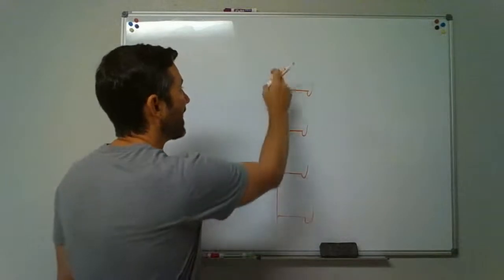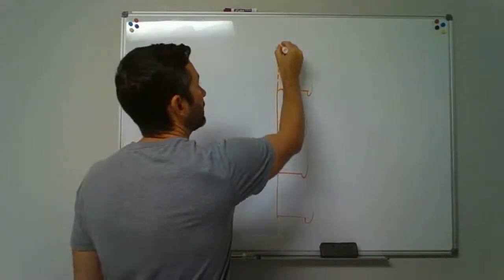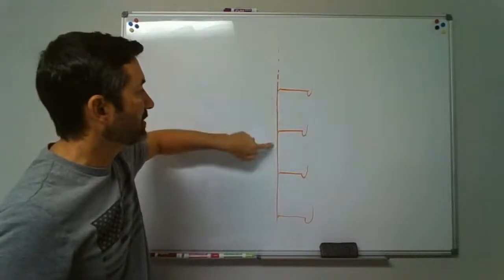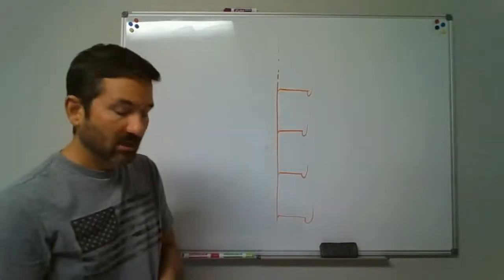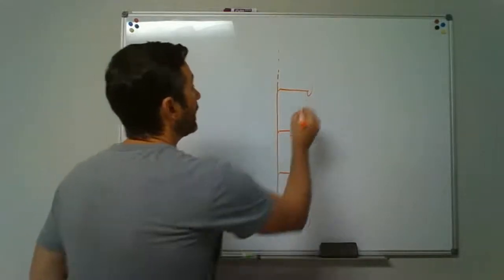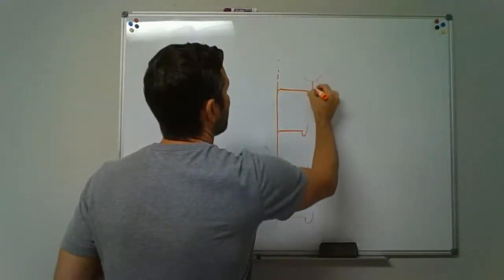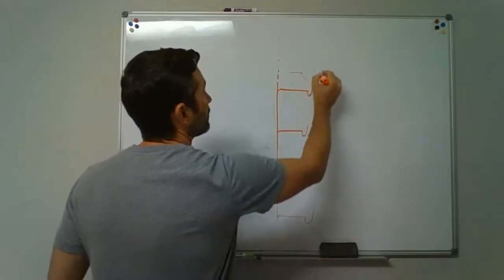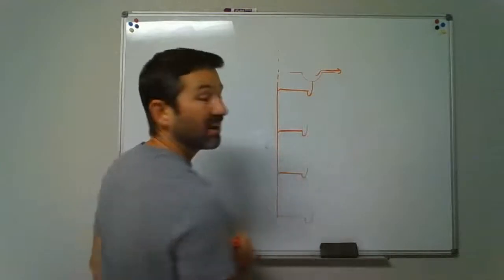Okay. Above the highest one, we've got the waste stack vent, which is going to be the same size as this. It says you can do some offset in it, and you can lay that down. But remember what we talked about? Here's the highest flood level rim of that sink, where the water is going to come out. We call that the flood level rim.